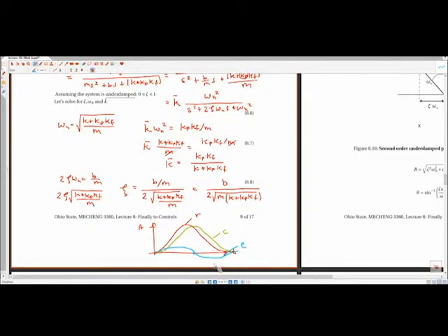And if I have, say for instance, this is our error signal, my input is a proportional gain of that, right? So if we're using proportional control, it's going to be the error signal times Kp, and that's what we're actually sending into the system. So say, for instance, Kp is equal to 2. That means my input signal is going to be, this is my best approximation of twice that signal. It's going to be equal to this, right? And if my Kp was 10, then it'll be 10 times that much. So I'm putting more effort per unit of error if Kp increases.